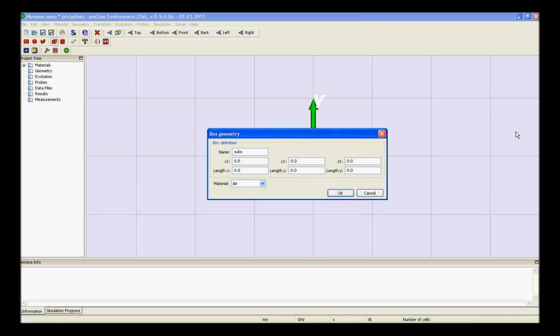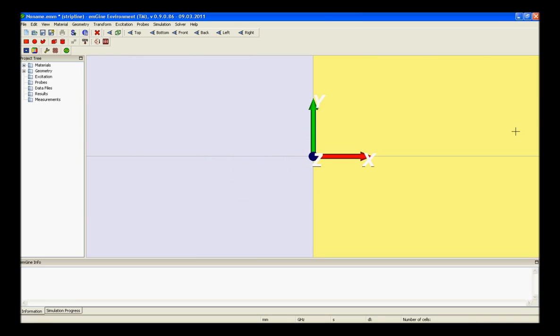The first construction step for modeling a planar structure is usually to define the substrate layer. This can be easily achieved by creating a brick made of substrate material in the box geometry section. Enter the dimensions for x, y, z axes. Select material in the material box as new_material.